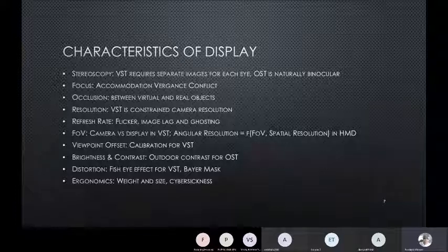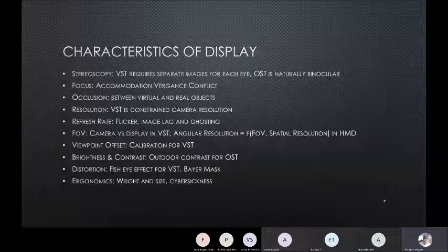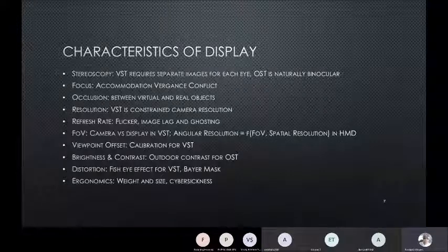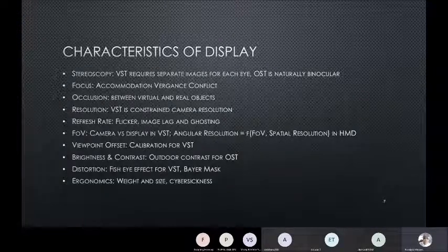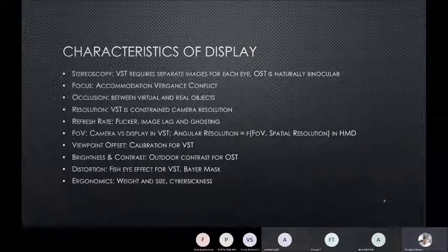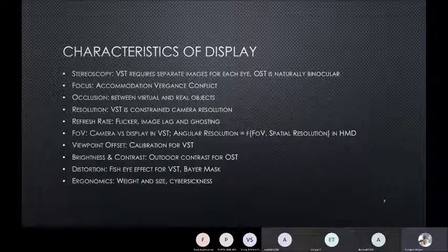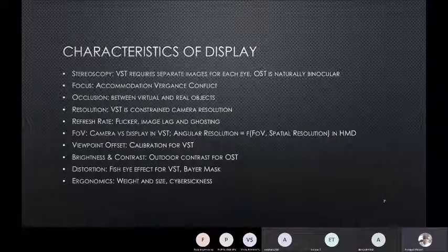So one way of solving this is using eye gaze tracking, finding where the user is focusing and creating the synthetic object at that plane only, or constantly sensing the depth of real life objects and adjusting the synthetic objects accordingly, which is very computation sensitive and so on.